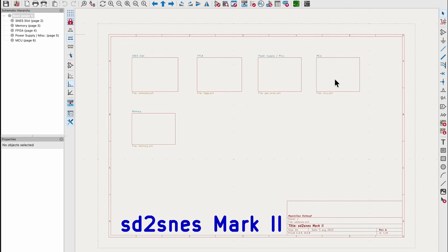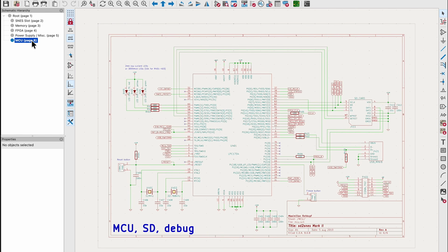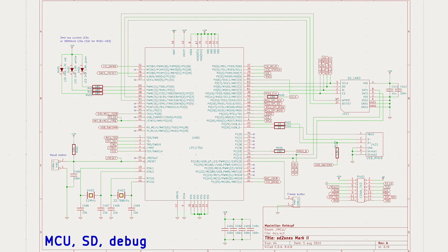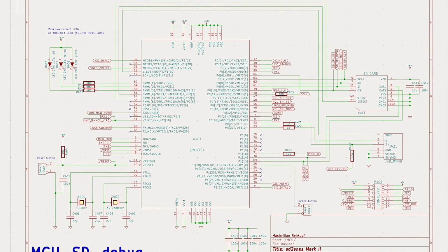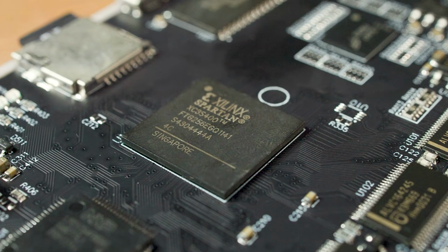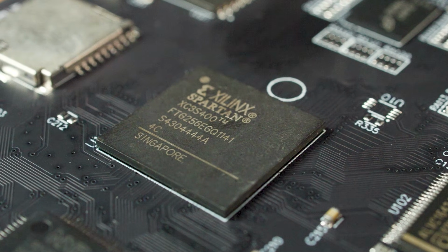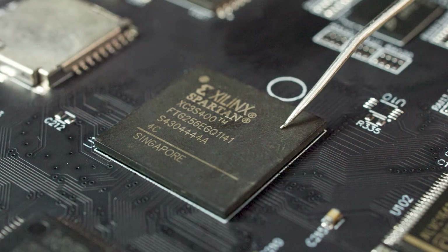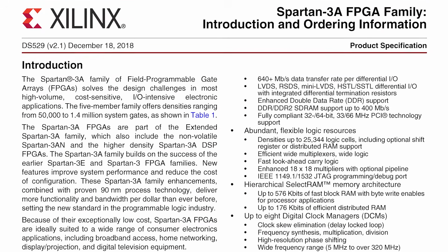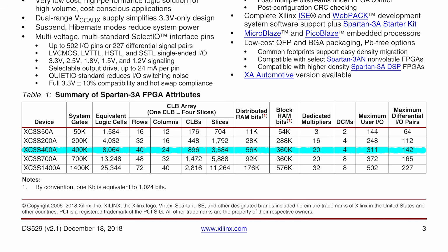According to the schematic, the MCU is functioning in a similar manner as the microcontroller in the final GROM99. It loads the game image from the flash card, provides the JTAG interface for the FPGA, and looks to drive various bits of the flash cartridge's overall functionality. So if the microcontroller is doing all of this, then why is there a Xilinx Spartan 3 series FPGA on board? This FPGA is quite a bit bigger than the ICE40 on the Game Boy cart, but it clearly isn't acting as the MCU. Well, SNES cartridges don't just consist of ROM chips.